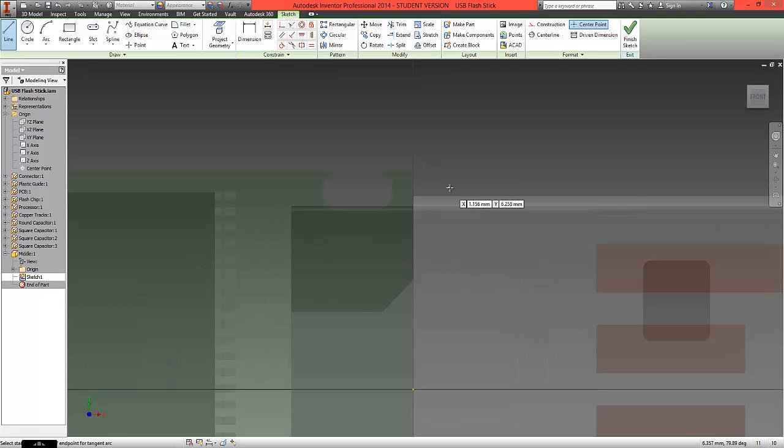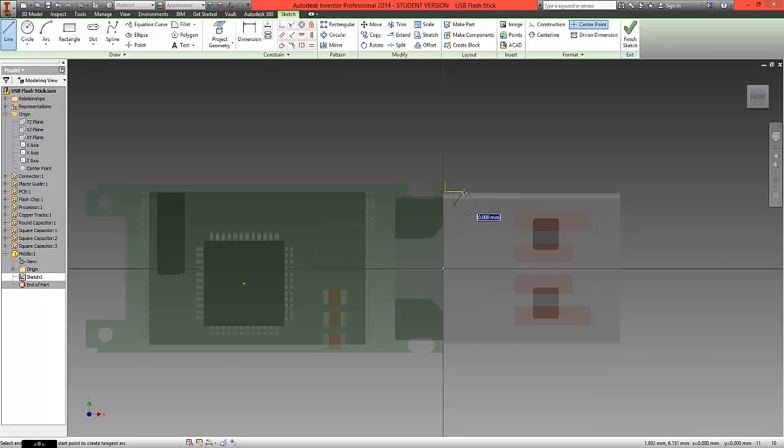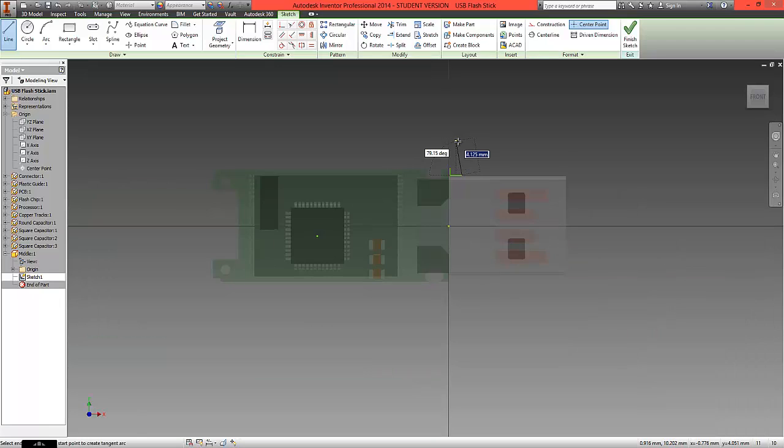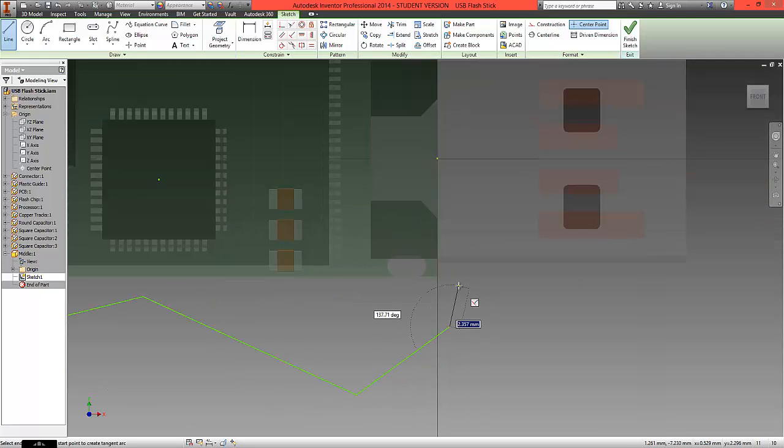You can zoom in, click once, and we're going to begin by creating a small ledge around which we can fit the USB. So this ledge now will stop this USB pulling out of its plastic casing. I'm now going to create a very quick and very rough design. You can create something a lot more complex using the line tool by simply clicking and moving the tool.